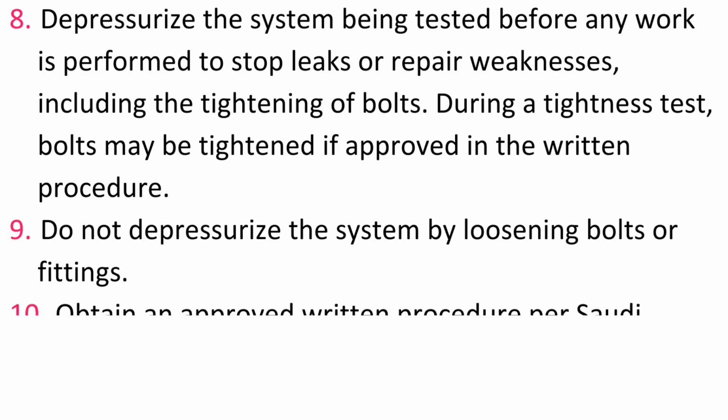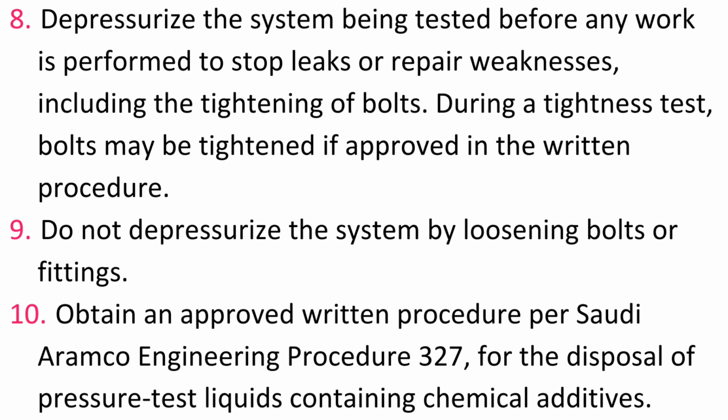8. Depressurize the system being tested before any work is performed to stop leaks or repair weaknesses, including the tightening of bolts. During a tightness test, bolts may be tightened if approved in the written procedure. 9. Do not depressurize the system by loosening bolts or fittings. 10. Obtain an approved written procedure per Saudi Aramco Engineering Procedure 327 for the disposal of pressure test liquids containing chemical additives.